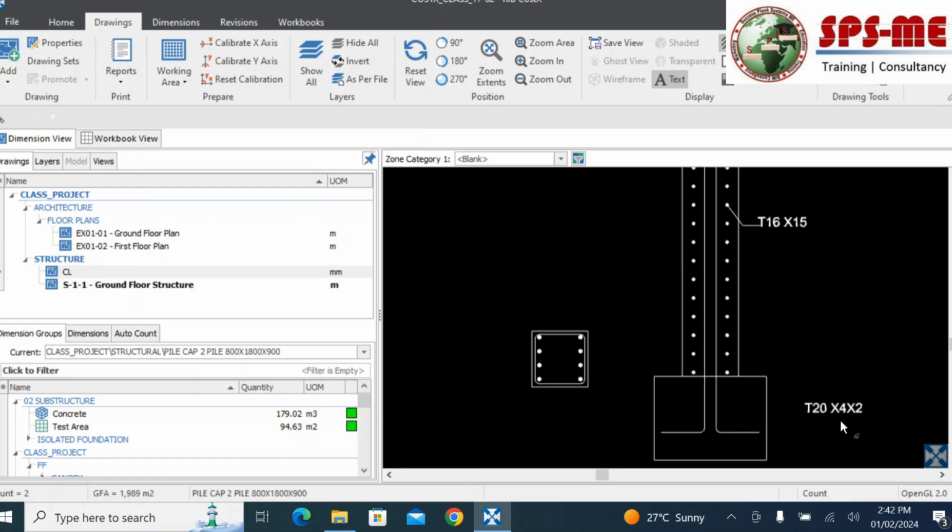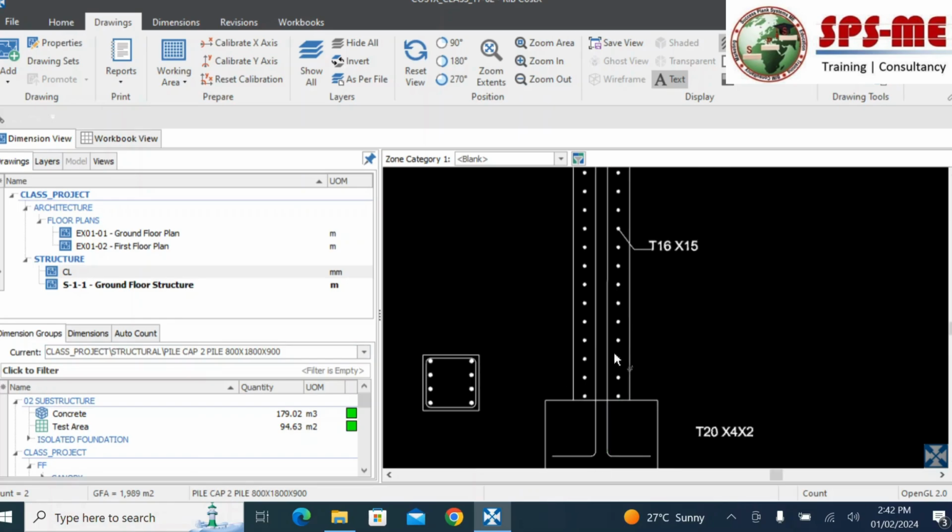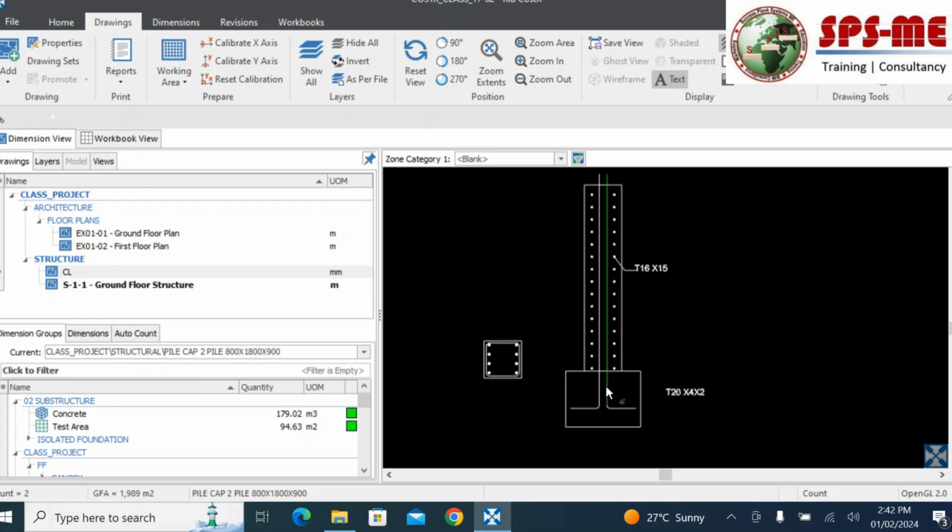So how can we take this? Previously we have added all the rebar. Normally rebar we measure by the length, and for 1 meter, what is the volume, that we have already assigned into our system. You remember that process, we did it in the last class. Now first I need to take this T20, the column T20 bar. What is the total volume? I need to take it.